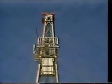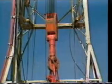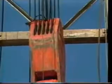The drawworks is a spool or drum upon which the heavy steel drilling line is wrapped. From the drawworks, the line is threaded through the crown block at the top of the derrick and through the traveling block, which hangs suspended in the derrick. By reeling in or letting out drill line from the drawworks, the traveling block and suspended drill pipe can be raised or lowered. Attached to the traveling block is the hook, which is used to latch onto the drilling apparatus necessary to accomplish the rotating function of the drilling system.